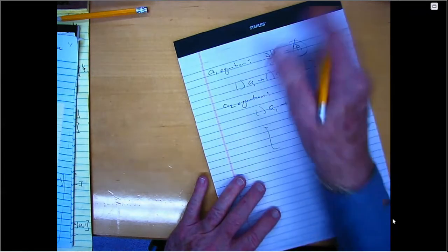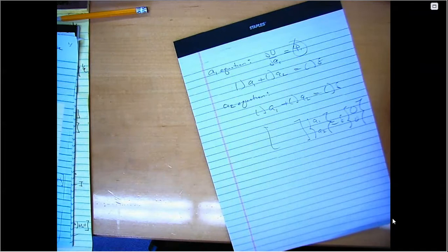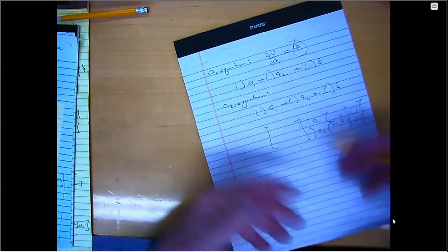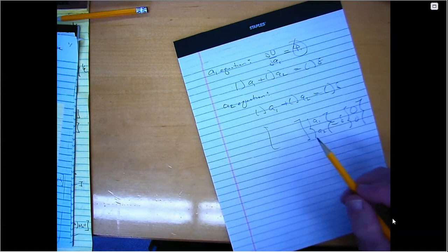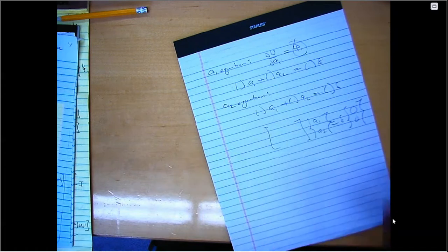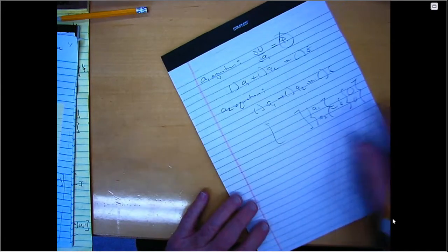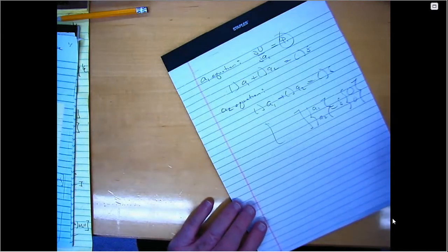If you only have one equation, you only have one A, then the opposite. And if you have 3 equations, you would have a 3 by 3 matrix and so forth. When we do the case when Gj is not constant, we will have the dynamic pressure inside the K matrix plus the term for work. How do we get that out for solving? Because we can solve for the A vector, but that A vector is dependent on the dynamic pressure. The answer is you're probably not going to get the dynamic pressure outside. So there's going to be some numerics.